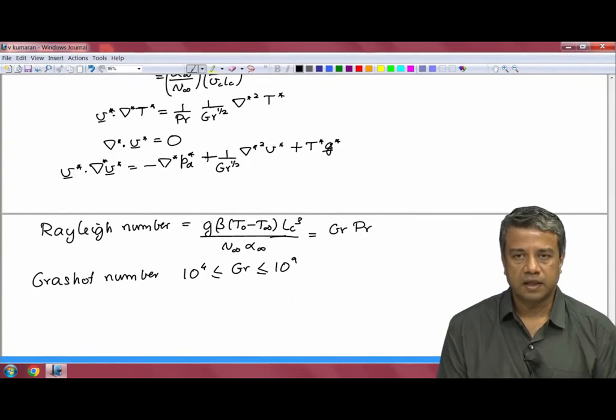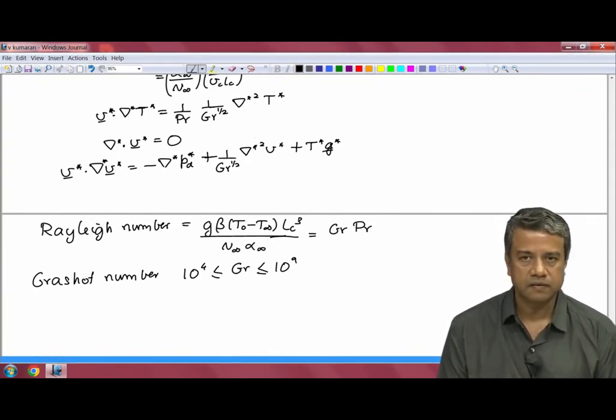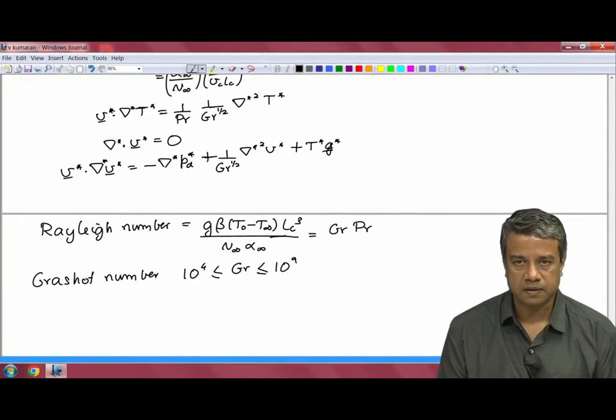However, if you neglect diffusion altogether, the equation reduces from a second order differential equation to a 0th order differential equation in the cross stream direction, and therefore you cannot satisfy boundary conditions. Physically, if diffusion is neglected, there is no transport from the surface, because transport perpendicular to the surface has to take place due to diffusion.